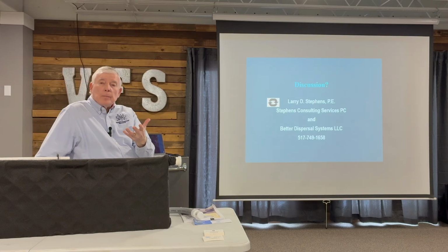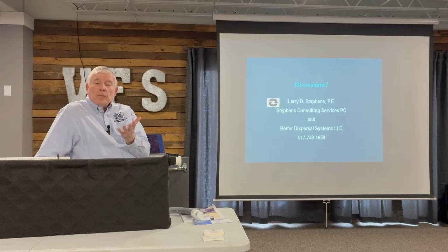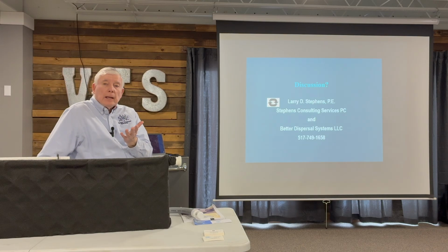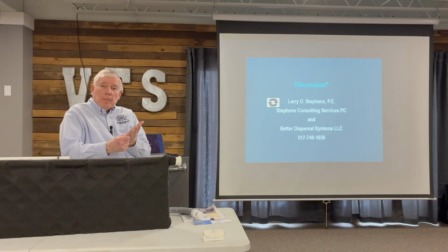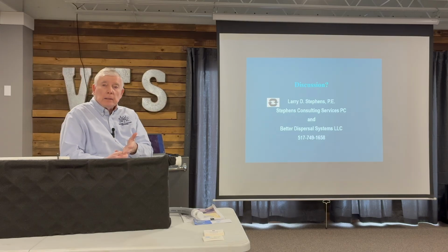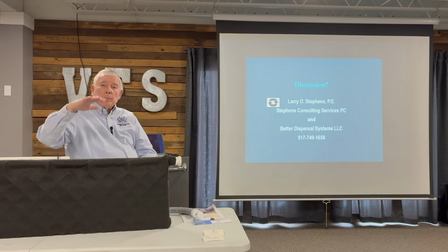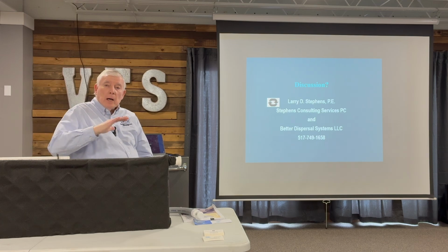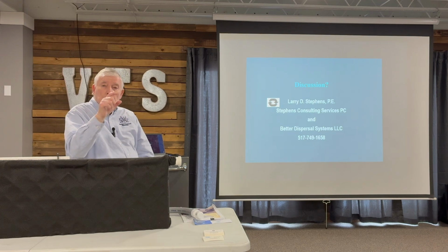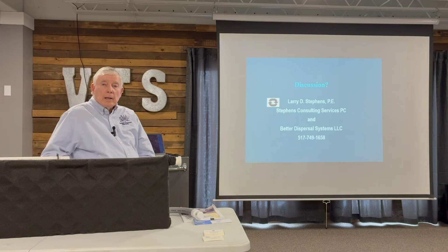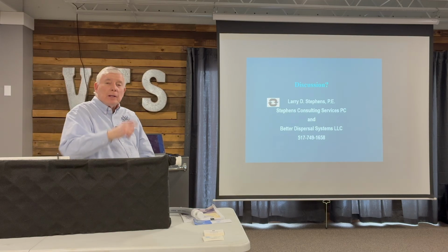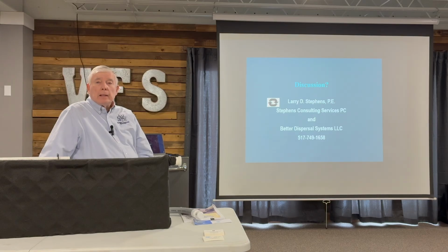Then I plug in the head loss information, the fittings, the size of the discharge plumbing in the tank, the size, length and type of material of the force main, and my residual head. It gives me all the data I need, gallons per minute and TDH. And if I don't like the number, I go back and change something in my design.